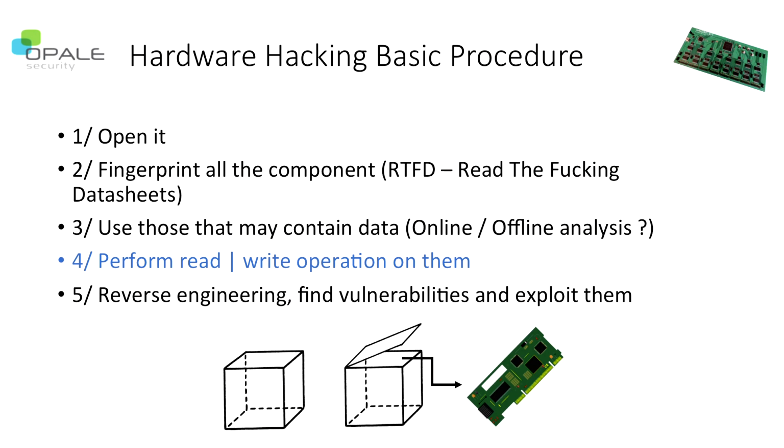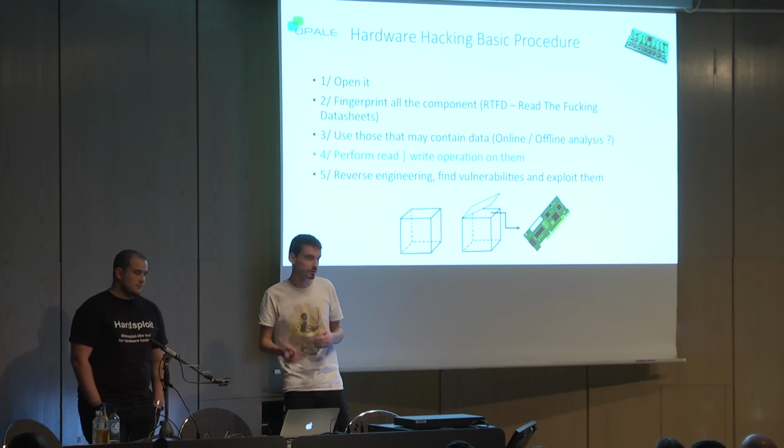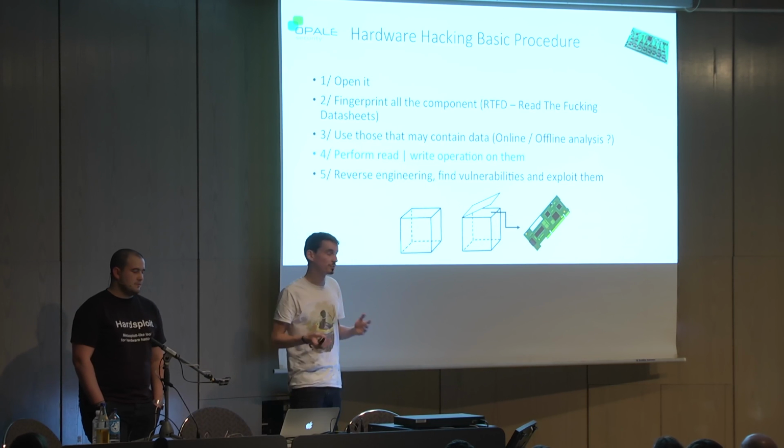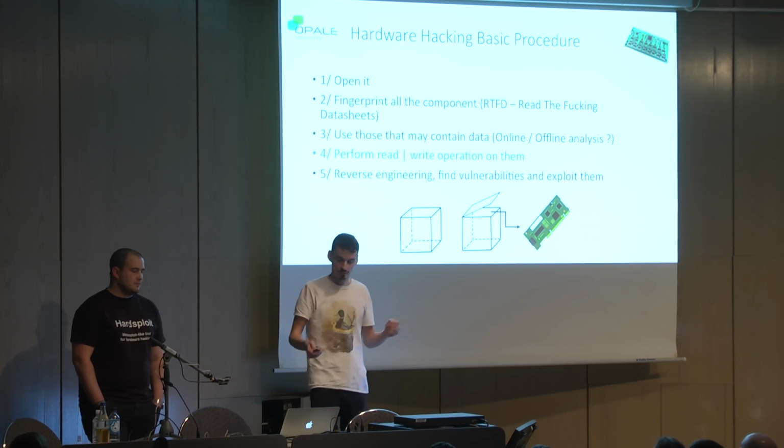When you have detected the interesting components, like memories or microcontrollers, you are going to use them. You have two ways to do that. You can unsolder the component and plug it on another PCB to work on it more easily. Or you can directly connect the tool you use to the component to perform an online analysis. Then, when you are connected to it, you try to perform read and write operations to access the data. And when, of course, you have the data, you are going to reverse engineer the process to try to find vulnerabilities and exploit them.